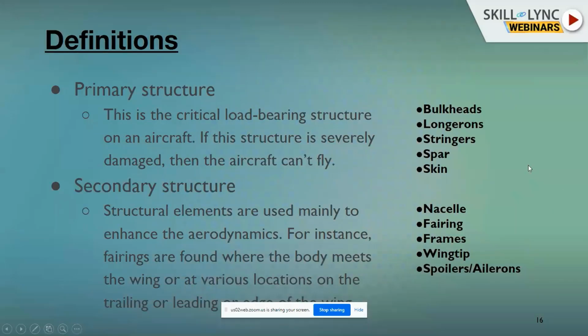Okay, now in structures we basically have three classifications: primary, and secondary, and in secondary there are categories A, B, and C. So for example, the winglet we call a category C structure. It is good to have, but not required. That is called a category C secondary structure. In primary structures, those are mandatory. You cannot avoid them. Without skin, the aircraft won't be pressurized or won't even fly, because your aerodynamic drag is disturbed, your flow is disturbed. Everything will move out of the aircraft.